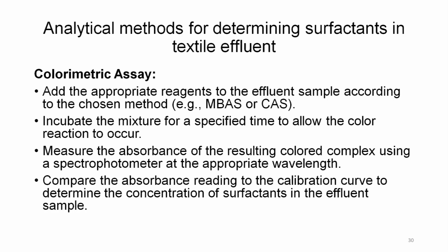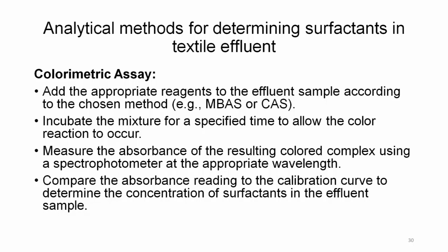Now, here you will see that because the color has to develop, therefore, a certain specific time period has to be left between the appropriate reagent, whether it is MBAS or CAS reagent, and the textile effluent sample, so that the surfactant specifically reacts with that reagent and develops color.